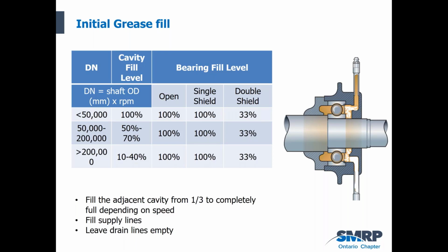Really, real quickly, what we need to think about is 2 things. First of all, how much grease do we initially pack into a bearing? So if it's a bearing that needs to be greased, the decision about how much we pack the bearing depends upon the physical size and the speed of rotation of the bearing. If the bearing is very small and or turning very slowly, we would literally pack the whole thing with grease and we're good to go.